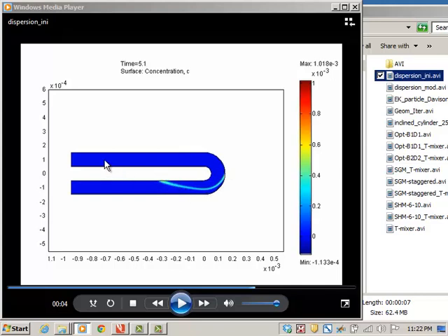The flow here is electrokinetic flow. So we have solved for the electric field, which is driving the fluid flow. Then we are solving Navier-Stokes for momentum balance, and also we are using the convection diffusion equation for solving for the concentration of this species. So we can couple all these different physics in this single software, and we can solve this multi-physics problem. And probably we're going to see some of these later in this course.